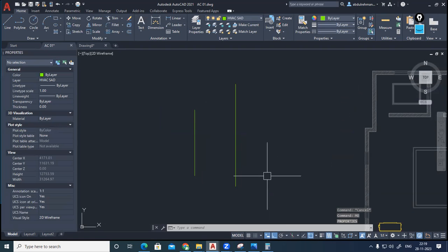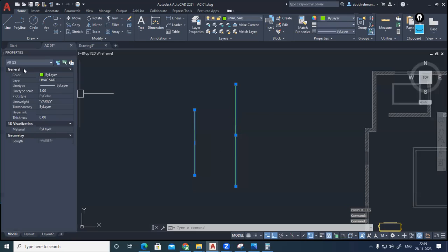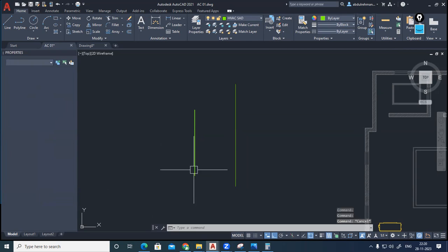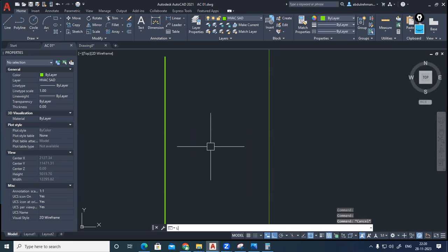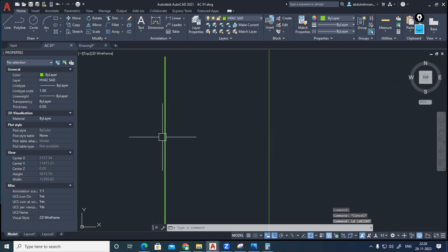MO, enter. Then select your polyline. You can see what object it is, polyline only. What object is this, line only. Okay, we are dealing with the polyline. Polyline has a global width value, 0, this one. How much has to be provided? 20. Select this one, provide 20, as the company has specified, enter. Now you can see, even if the line weight is off, the thickness is visible.